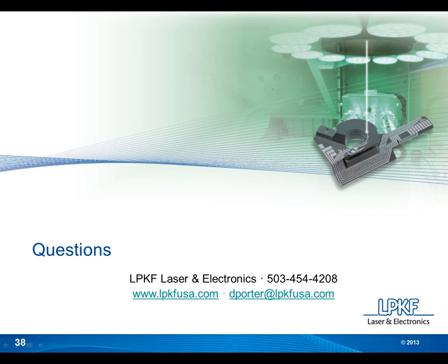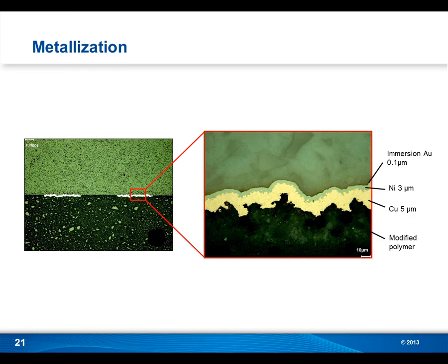As we saw there, there's a typical thickness of electroless plating, which is not quite as thick as you see with most standard 1 ounce or 35 micron circuit boards. Here the plating is typically quite a bit thinner. We see about a 5 micron copper here. It can be 8 or 12 micron copper. So as we get a little thicker, of course we can carry more current.